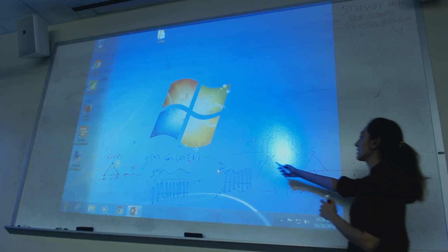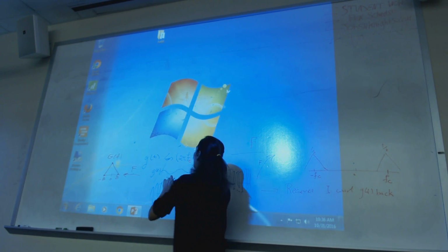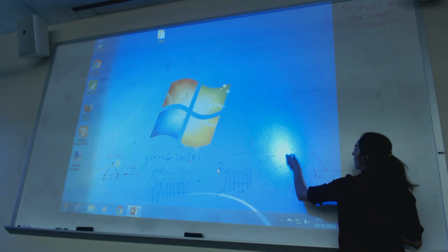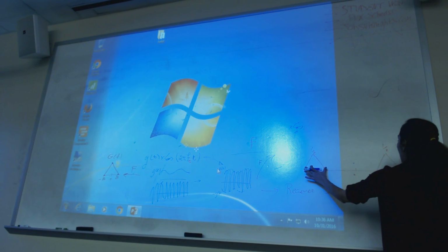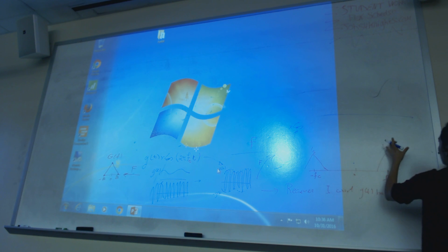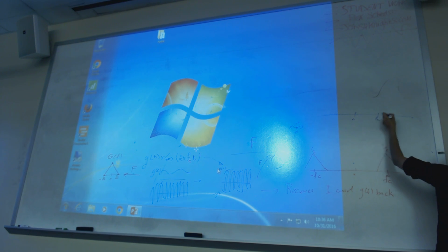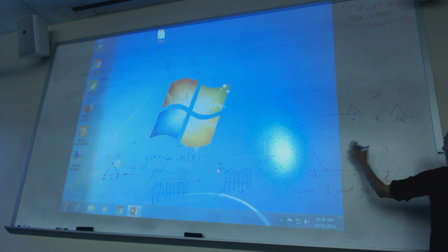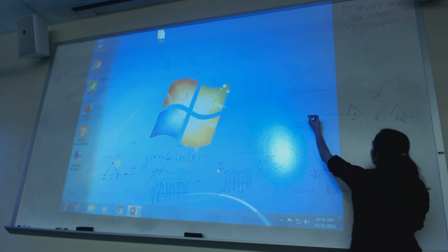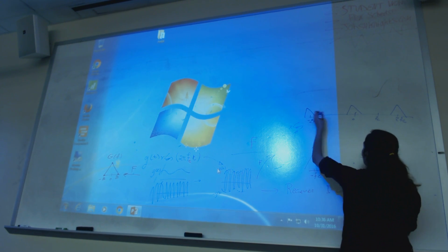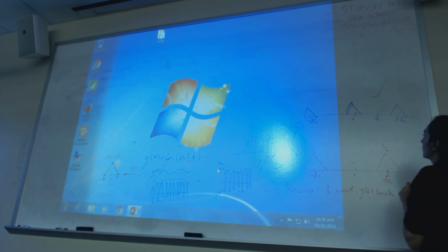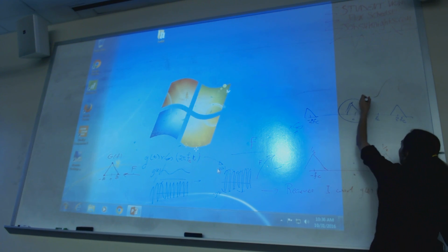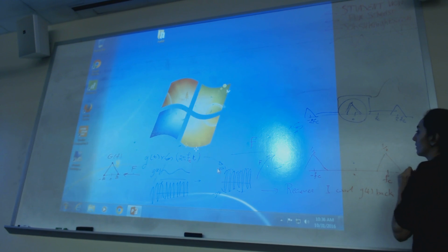So we know the shifting is basically multiplication by cosine. Multiplication by cosine or sine basically shifts the spectrum. So if I multiply this again by another cosine, what happens? I shift this to the right by fc. So instead of fc now I have 2fc, and minus fc goes to here, shifted to the left. So we get minus 2fc, and another one here. So this is what happens. Now this looks exactly like my G of f. So I can put a filter, let's say here, and then extract my G.